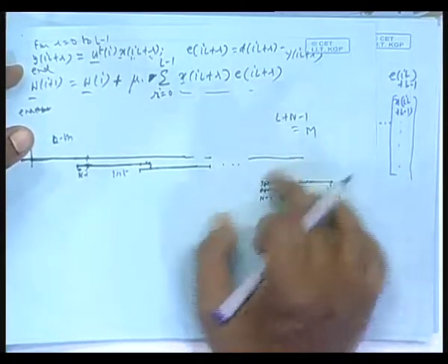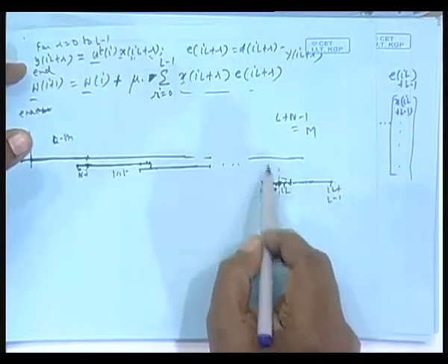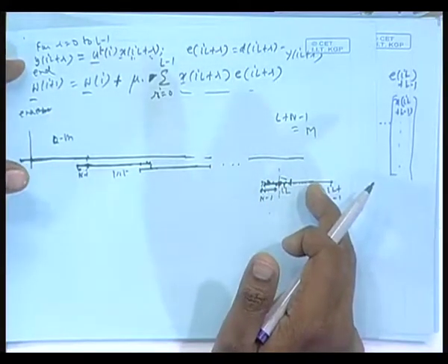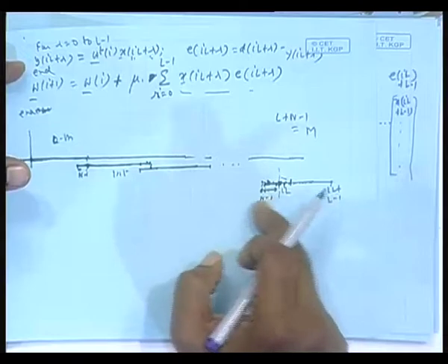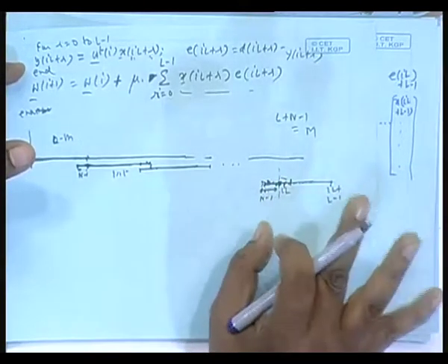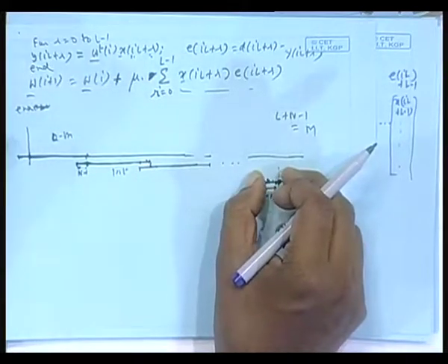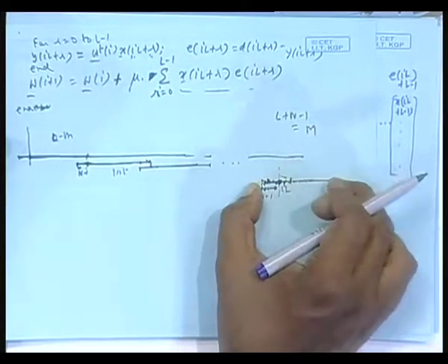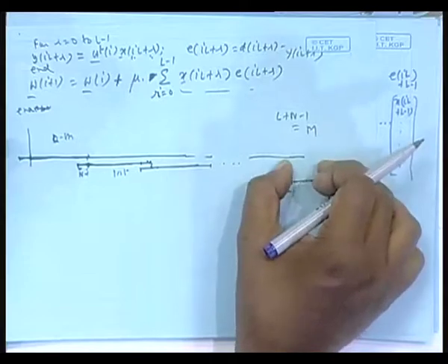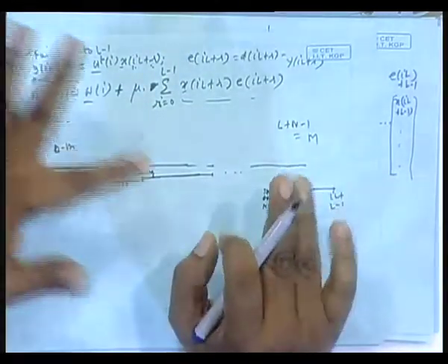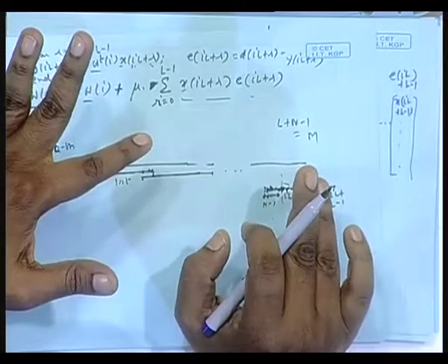This I need, because I am doing the overlap save method of filtering. So, the circular convolution thing was there, and throw away the first n minus 1 sample output and all that, add zeros. This filter vector is length n, and this is L m. So, add those difference of zeros and then circular convolution. That we did yesterday, now overlap and save method.